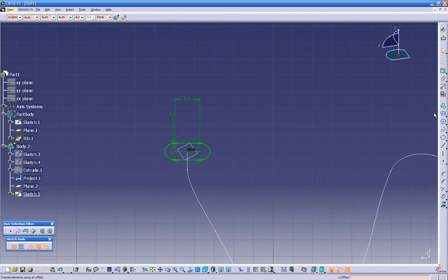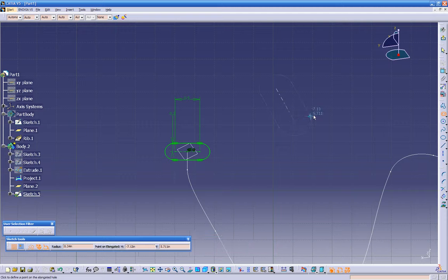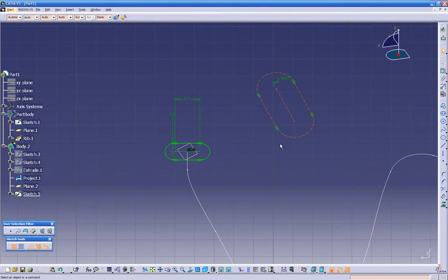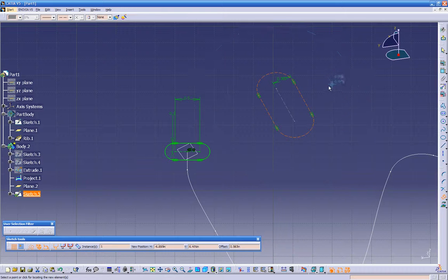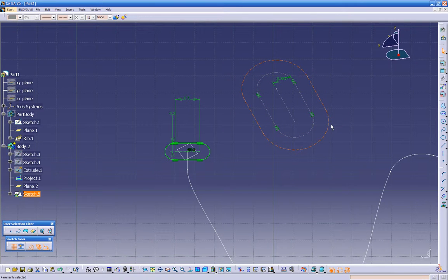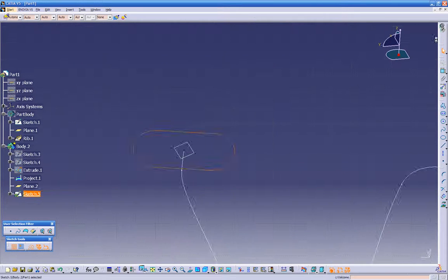What I was gonna show you over here by this offset, if we have this, what we can do, just highlight the stuff that you want to offset. Just click on this option right here, and you can go bigger or smaller. Or if you hit the tab key, you're gonna come down here and make it 0.300 and click OK, and that's our dimension right there. So that's offset, but we don't need this anymore. So let's get out of here.